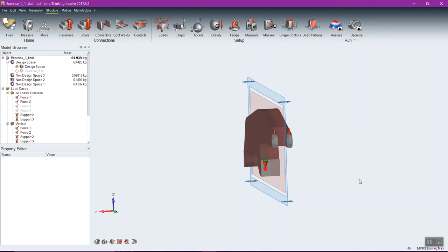We do incorporate heat as a thermal load, but then that's just the load using the coefficient of thermal expansion. It will expand the part, and then because of the deformation, it induces stress in there. So we do allow thermal, but it's just a simple delta T in that case. If you want to do heat transfer, we do support that with one of our other solvers, but we don't do optimization against it. Optimization right now is strictly linear.